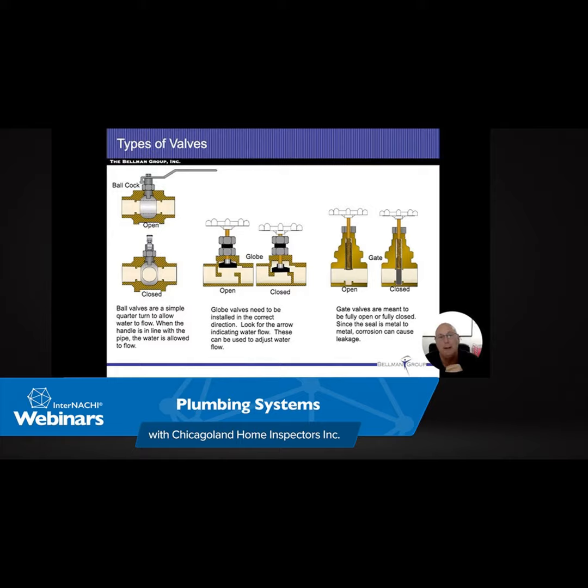Since most of the homes in this area, or I should say older homes, do have lead service lines, I explain to my client, just treat them as if it is. I don't even encourage testing for lead in the water anymore, because if I don't get that water sample that was in the pipe for 24 hours or so, then I'm not going to get a good sample. It might come back negative.